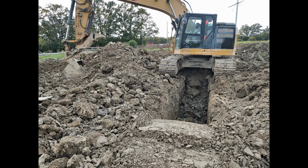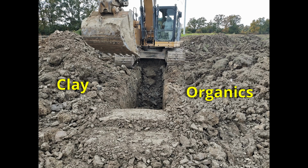I want to warn you that no one, including yourself, should ever enter the trench that's being dug for the groundwater dam. People die each year because the walls cave in and bury them, and this only takes a fraction of a second to occur. Soil that is low in clay, including organics, is piled on the other side of the trench. This soil will not be placed back in the trench.